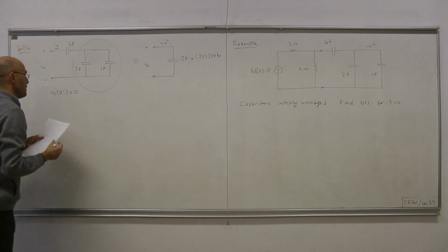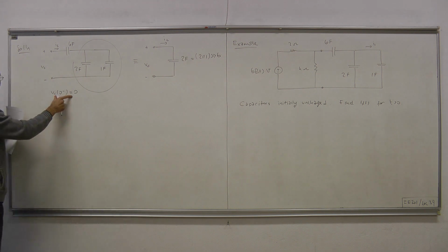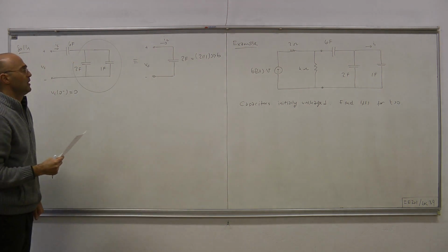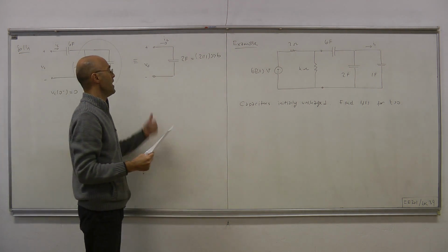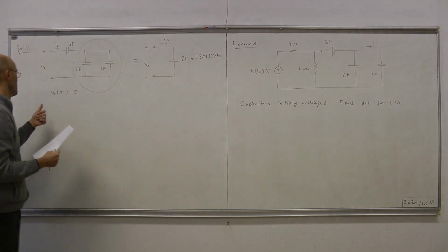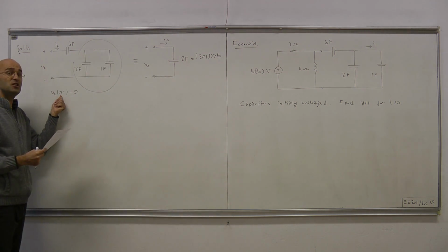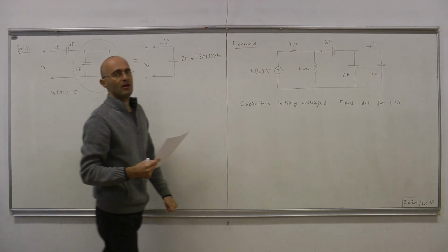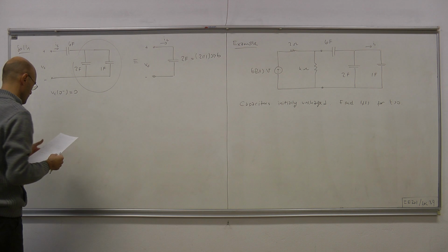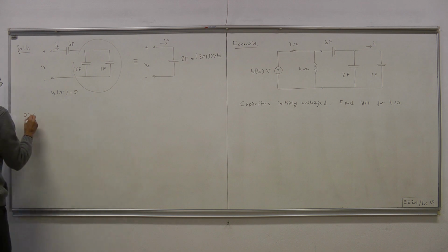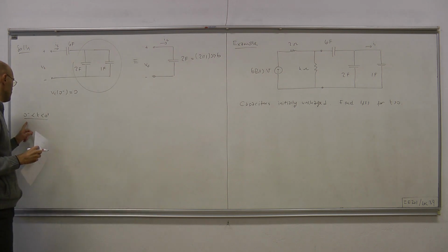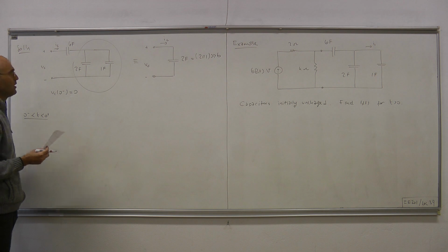Okay, and now this is the initial voltage of this equivalent capacitor. Now what we have to figure out is what happens to the voltage, or what's the voltage at T0 plus, due to this impulsive voltage source. So let's perform the analysis for this infinitesimally small interval from 0 minus to 0 plus.